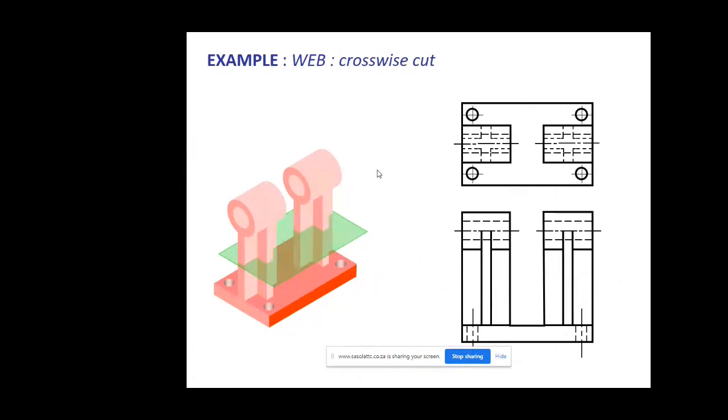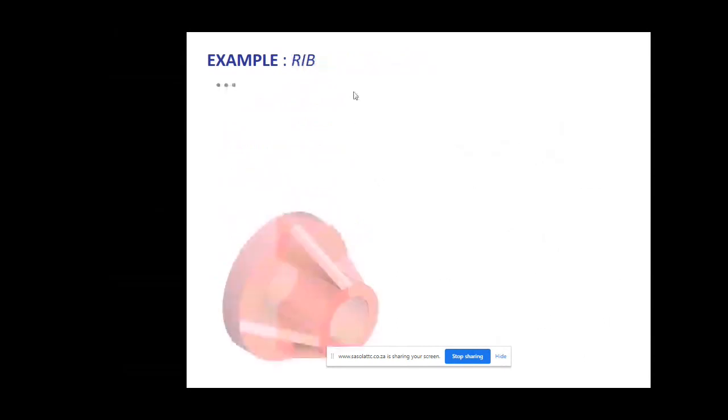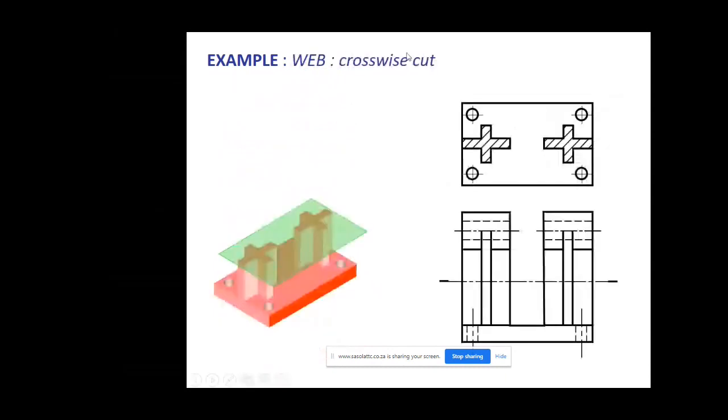So this is the cutting plane, as you can see on the front view. And then from there, for you to see a full sectional top view, you need to imagine the top part being removed. And then you'll be remaining with what has actually been exposed, because the main object of sectioning is to expose the inner part of a drawing. And then this is now how it's going to look. Apologies for that. And this is now a solution of how it's going to look.